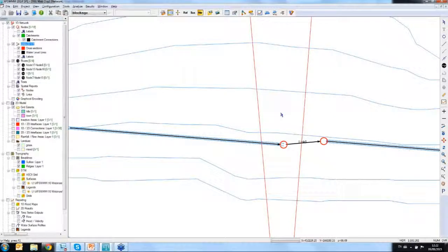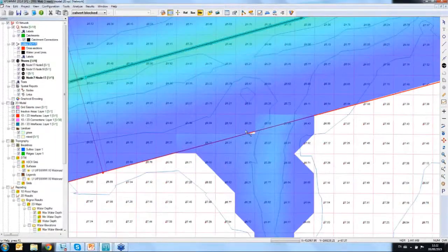And a follow-up question, which was looking at the 1D with the 2D link. Obviously, the grid square sizes then, when it comes to analyzing the overland flood routing with the 2D, the choice of grid square is important to get the accuracy of the breach, if you like, over the riverbank as you're showing there right now. Yeah, so obviously the smaller your grid is, the more accurate analysis you will have. And if, say, this is 10 by 10 at the moment, right? So if we had 100 by 100, maybe it won't even show it. Yeah. Because the average level of the cell would be different.